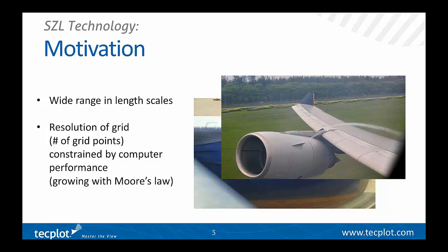It's like a big tin can. When the nose of the airplane is high, you're at a high angle of attack, and it creates boundary layer separation on the wing. That vortex then will help keep the boundary layer attached. But you don't want it to remain attached too long because you'd like the wing to stall inward rather than at the tip. So you don't want the vortex to be too powerful.